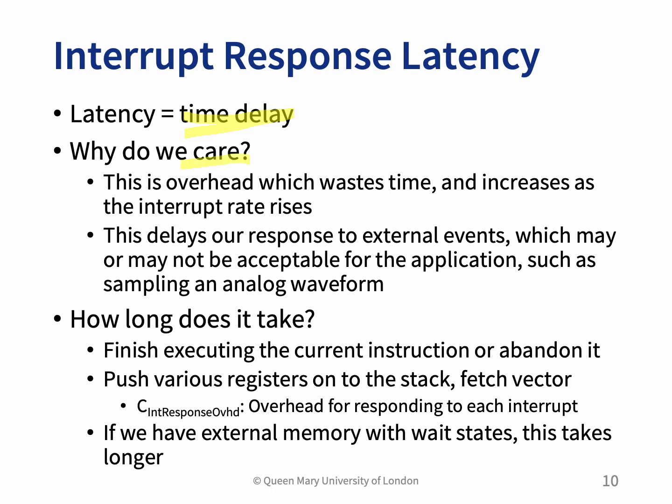That is why we care about it very much. If you have a high amount of latency, that means you have a high amount of overhead that will cause a lot of time wastage, and this will increase the overhead because the interrupt rate rises. So it doesn't mean that having interrupts is good news. As long as we properly optimize the amount of interruption, then we can minimize the overhead and also minimize the latency, right?